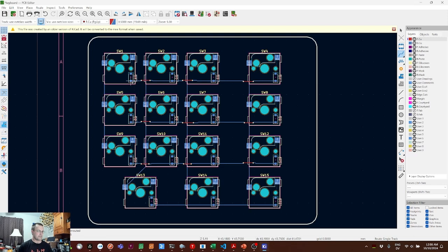But the basic idea is that having the microcontroller send voltage down the columns and then detect which row the voltage comes out, it can scan through 15 key switches using only 8 I/O pins, 4 rows and 4 columns. With the 24 I/O pins on our microcontroller, this can scale all the way up to 12 by 12 or 144 keys. This is how larger keyboards are built, and it means the same exact system can scale up as far as you want, pretty much.